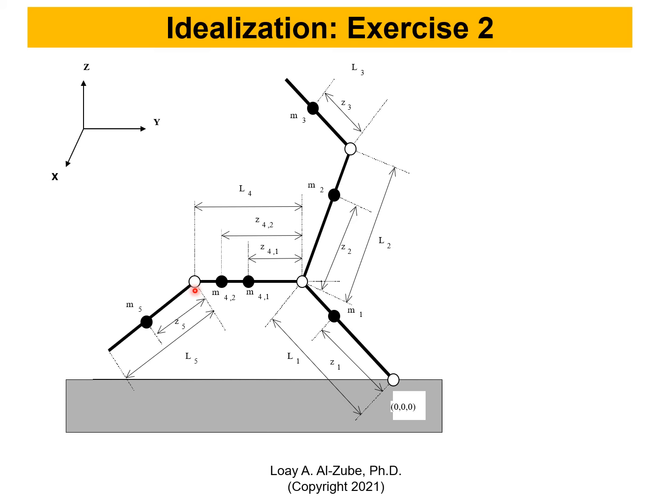So our relation matrix gives us, from its name, the relation. It shows you the connections and it shows you the mass points. Now, how many mass points do I have here? 1, 2, 3, 4, 5, 6 mass points, correct? How many segments? 1, 2, 3, 4, 5 segments, correct? Now, in your relation matrix, the number of rows is equal to the number of masses.